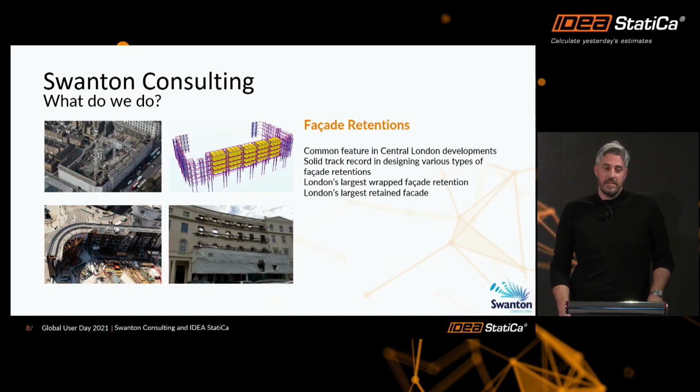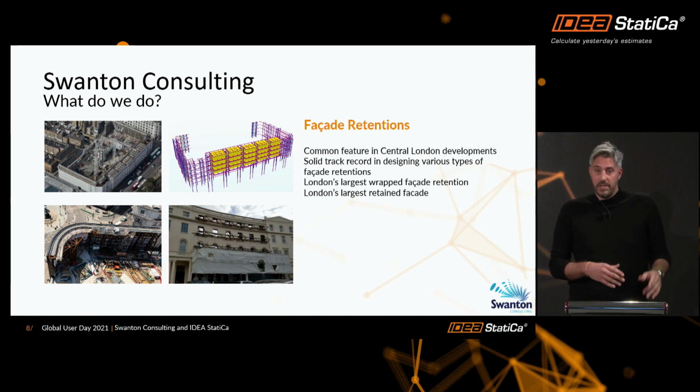Also, we are a diverse team with several backgrounds and different cultures, and we do share a love for historic buildings. So we are offering services that are partially incorporating heritage structures or parts of the structures like facades, and we're developing retaining, supporting schemes, but also the means and ways to incorporate them within the main new structure and the whole structural scheme, which is a quite challenging environment since the global deflections need to be extremely low to avoid any damage.